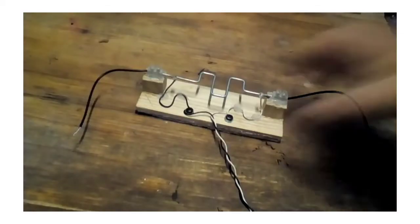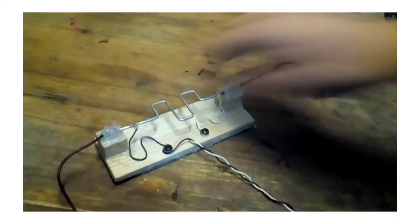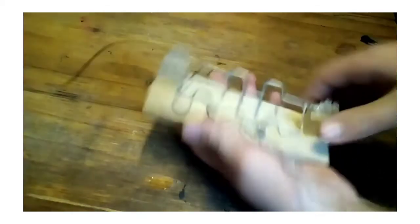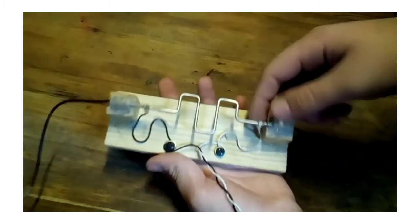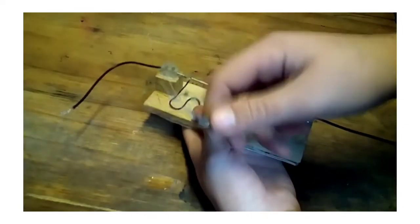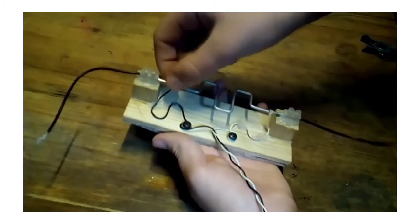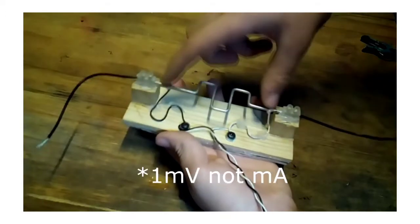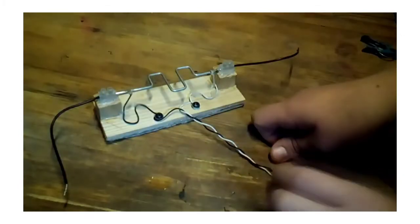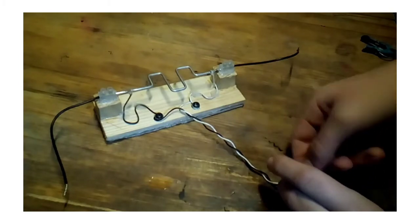Hello, today I will show you a homemade shunt for measuring DC current. So let's test it. It's really easy to make. This is just thick aluminum wire, and measuring wires are connected just there and there. One millivolt there means 1 ampere. So you just take the wire and measure where you get 1 millivolt at 1 amp,